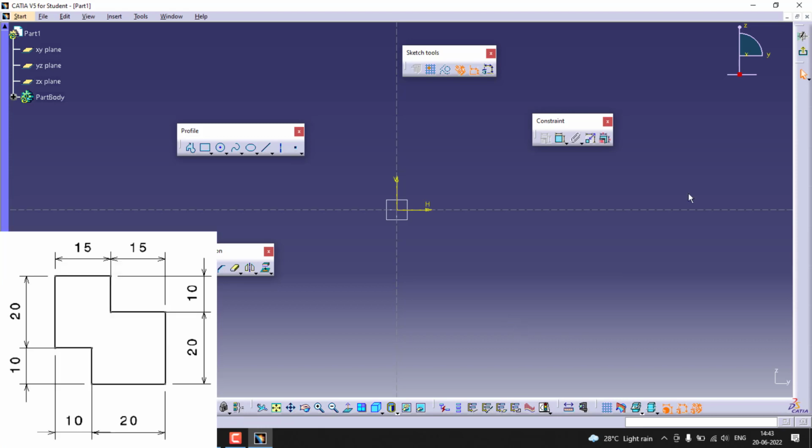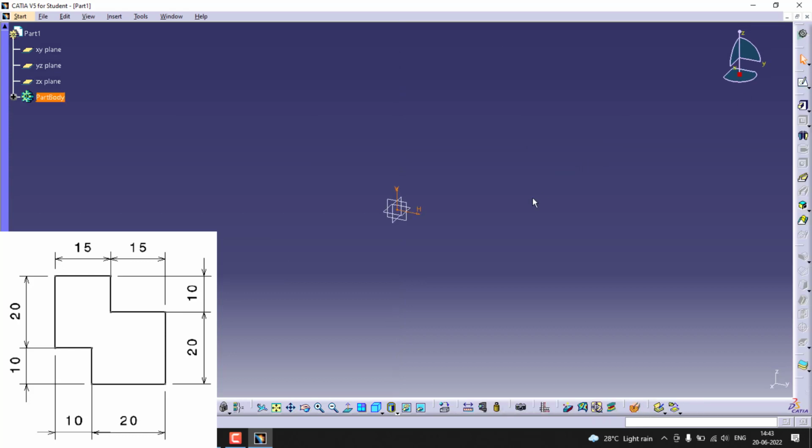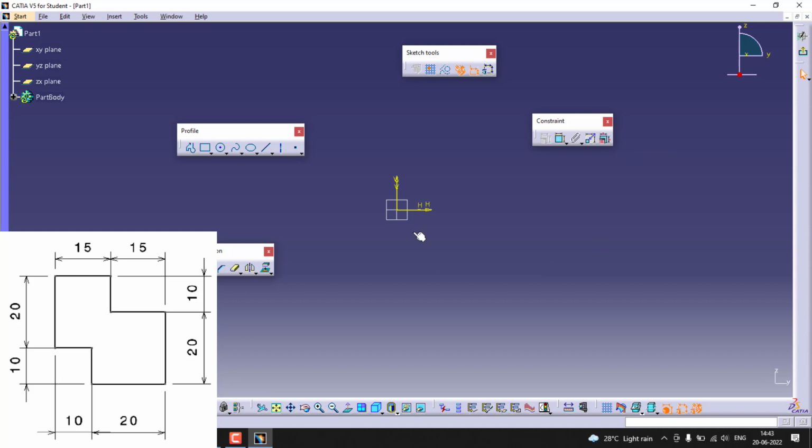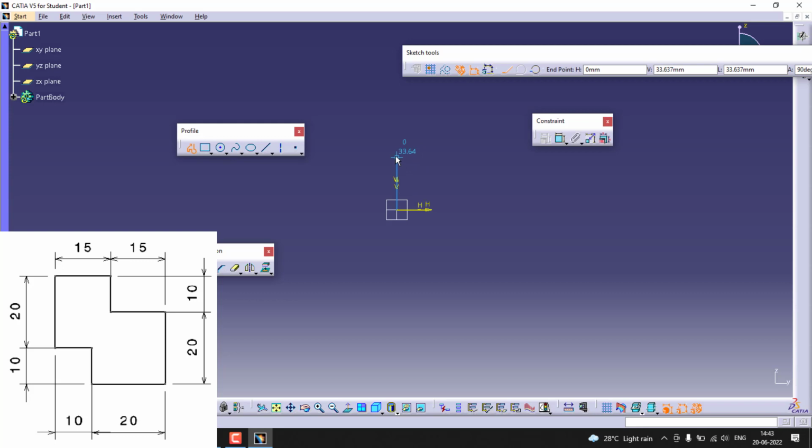Now instead of doing a trial and error method, drawing the rough sketch, what you can do is start with the manual dimensioning at a time by using the sketch tools. Let's say I'll use the profile tool. You can drag it up from the origin, and you can use the tab to jump to the length, L20. Okay, like this. So same thing in the sketch tools.